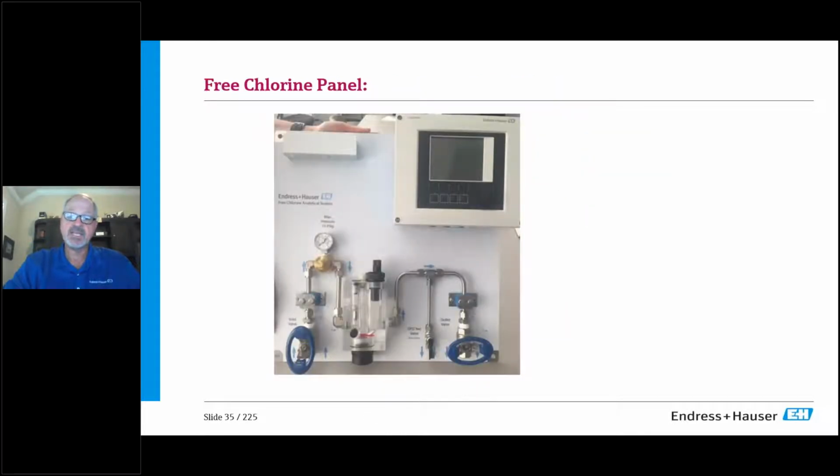And we package that nicely. We put it in here where you have the standard flow block. You notice how we kind of trapped it so it always has a nice wet sample in there. We've got some valves and gauges on it, and then the standard transmitter. So that's our chlorine solution.